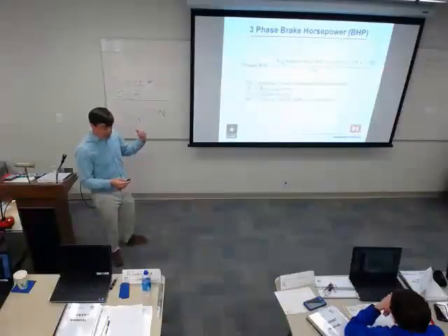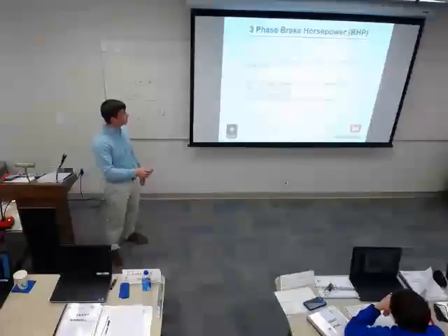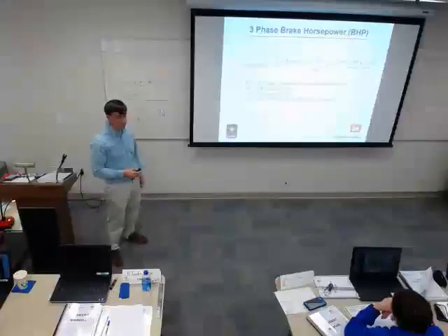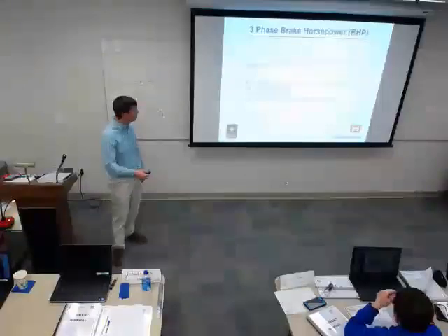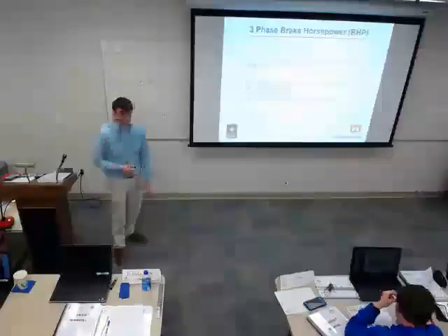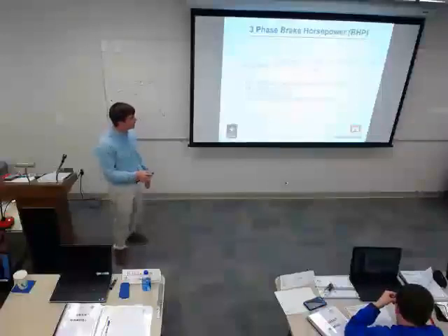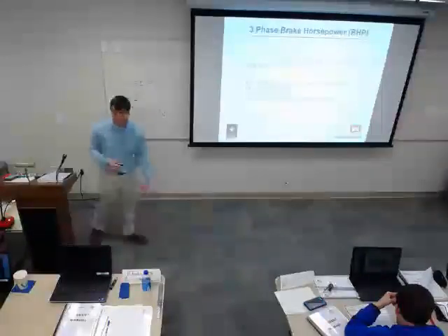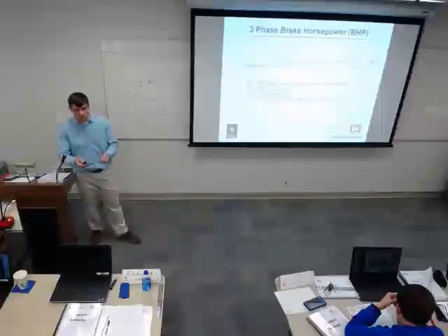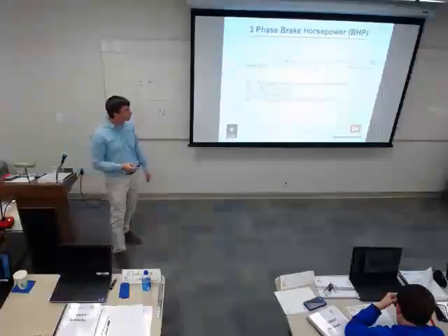And that was for single phase. For three phase, it's basically the same equation, except you add a square root of 3 in there to account for the three-phase operation. You shouldn't have to do this stuff. I just wanted you to mostly be aware of this. If you're trying to figure out power and you're just using the numbers you're getting off a standard voltmeter, it's probably not going to make sense.